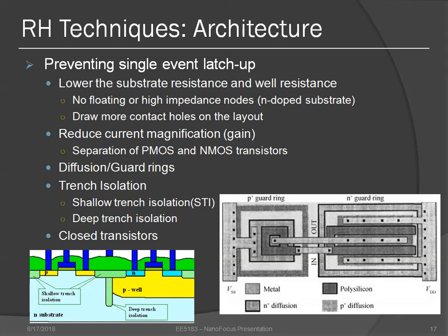Leakage between devices can be alleviated by surrounding every transistor with a P+ diffusion guard ring. You can see here there's the guard ring that surrounds a structure. And this forms a channel stop by locally increasing the threshold voltage of the oxide to a very high value. These types of guard rings also help mitigate single event latch-up effects in CMOS structures. Basically, they help isolate neighboring circuits by breaking up the parasitic thyristor structures that can latch up.